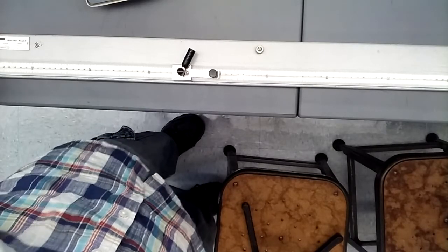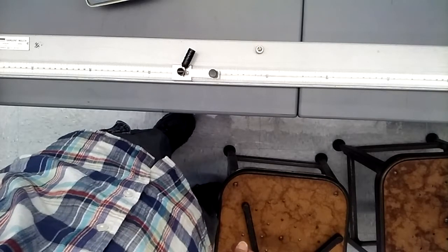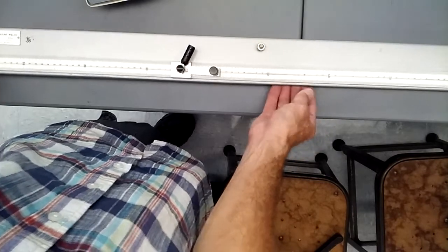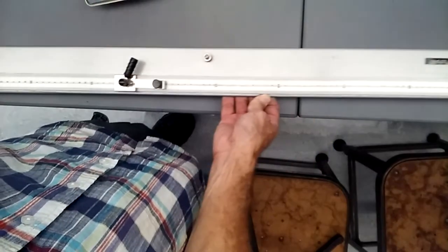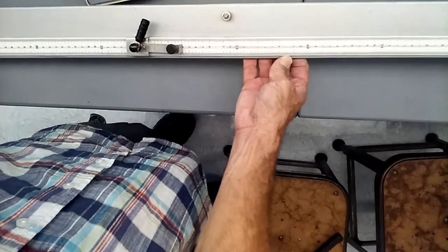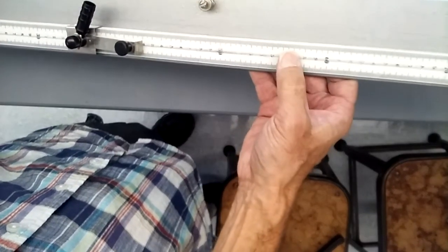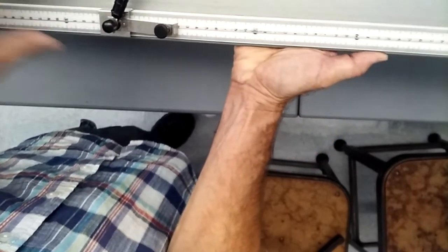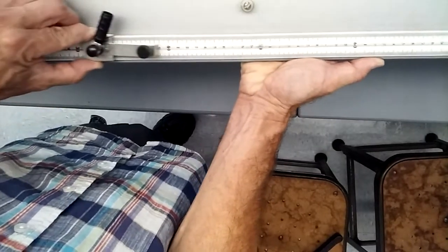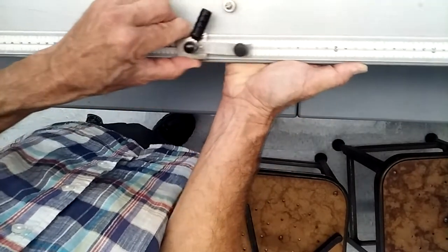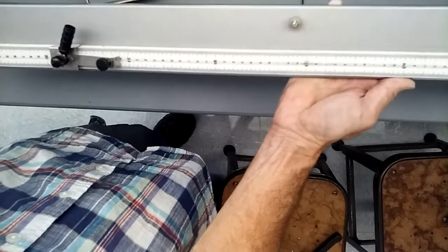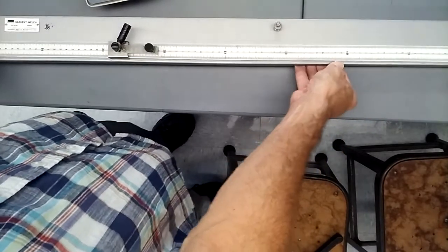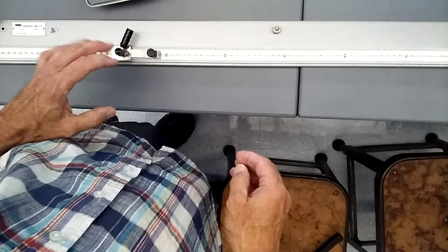Okay, so let me show you some of the equipment we're going to use. The R1 and R2 that can be varied are actually one device. They're combined in this one big long device here. This is the slide wire bridge, and I don't know how well you can see this, but there's a real thin wire on it, and there's a meter stick, okay? And so you can slide this contact different places, and you can select whatever position on the wire that you need. And basically this wire on top of the meter stick will serve as both R1 and R2.